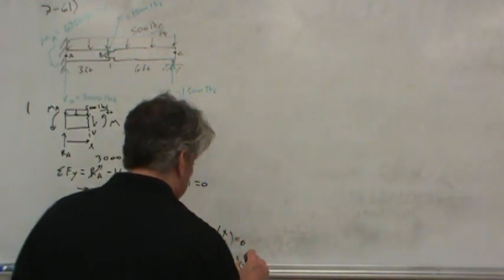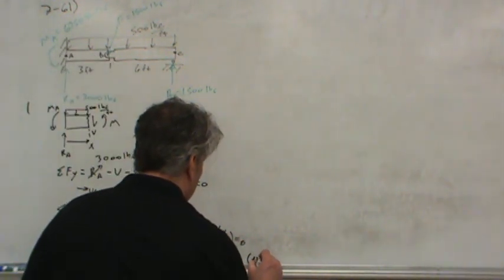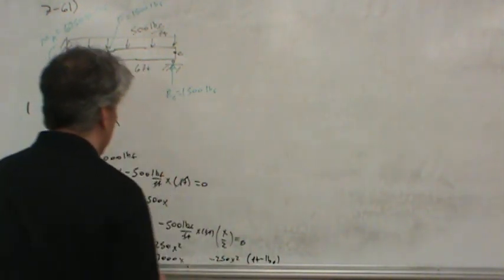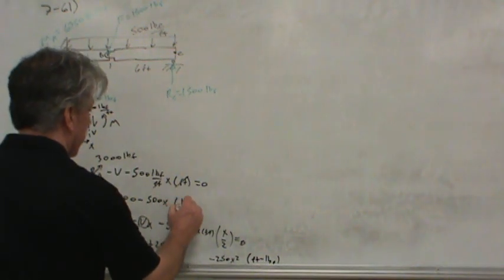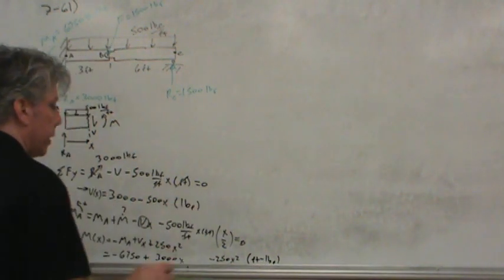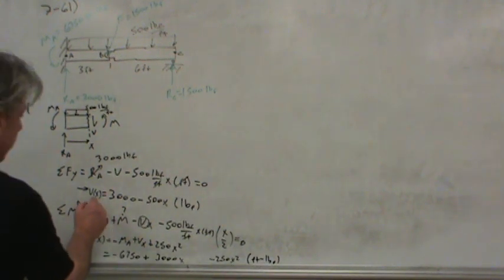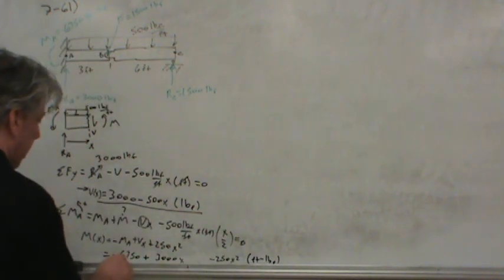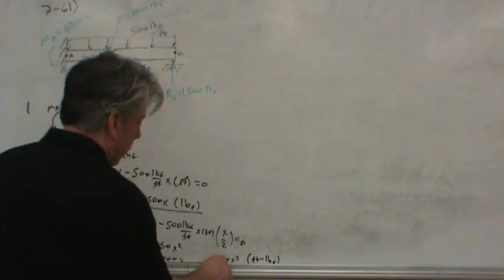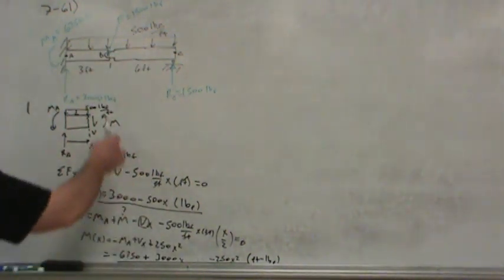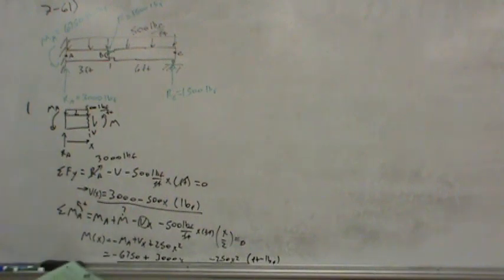And of course the units will be in foot-pounds, whereas the units here are in pounds. And of course we need to plug x in the proper units of feet. All right, so we worked hard, but there are the equations that we need for the shear and moment, at least in the segment from A to B.